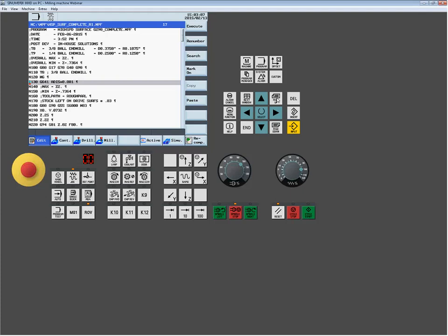We are always what's called upwards compatible. So what that means is we always want to allow programs that were written for an older machine or older control to be able to run in the new system. So we never get rid of commands, but we don't want to change the functionality of a command all the time because that can get a little messy. So sometimes we'll just build a new cycle. So originally we had G64, then we went to G641, and then we had a G642, and now we're up to a G645.